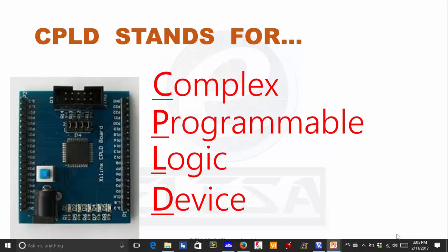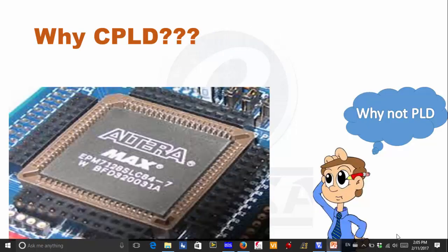You might have been wondering why they didn't choose to scale the existing architecture instead of creating a new one. To clear your query, let's take an example. Consider scaling of 16V8 PLD to make 128V64. Such a device would have 64 input pins, 64 I/O pins and some number of variable product terms, say 8 for each macro cell. The question is, could it be as flexible and efficient as 16V8?